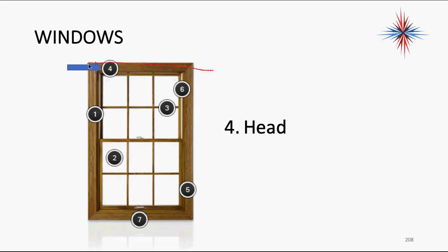We're worried about the window head. That's at the top of the window. What's it built out of? What's the material that's anchoring this window? If it's a steel beam, I have a possibility of a thermal bridge. We're worried about the window jamb. That's the outside components. What's it made out of? Is it metal? Is it wood? Is it plastic? We're worried about the sash. We're worried about the sill. A lot of times the sill might be stone or marble. It might not match the rest of the window, and has a different heat loss and heat gain.